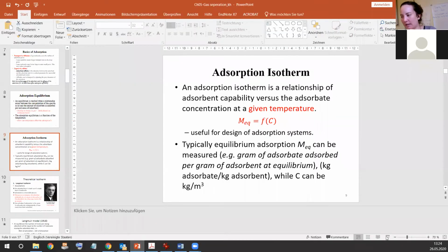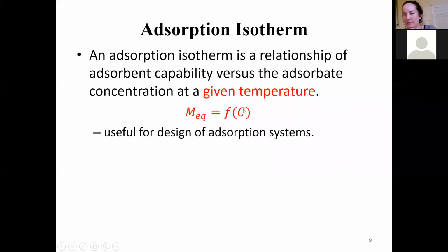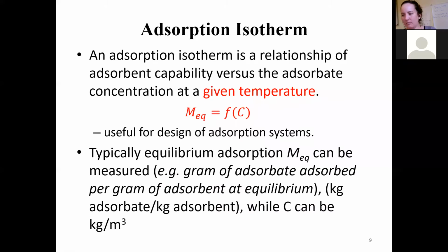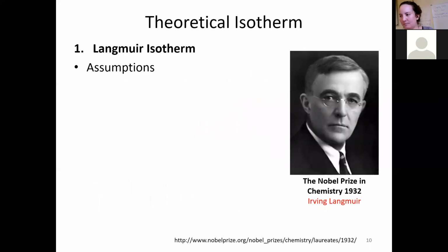When we're talking about the Langmuir isotherms, this depends on the pressure, this depends on the concentration, and so this equilibrium value, the mass of the material that is bound, depends on the concentration, the temperature, and the pressure. Typically this value is given as grams per gram: gram of gas material that's getting absorbed divided by kilogram or 100 grams of adsorbent material.